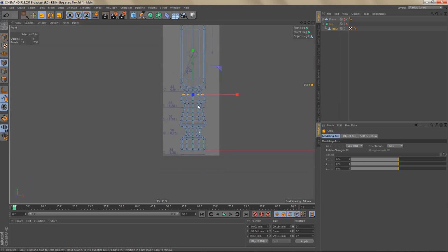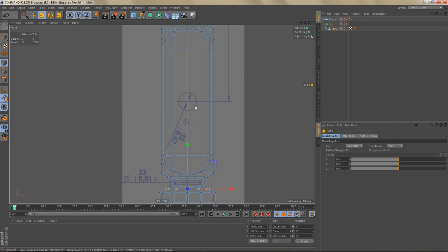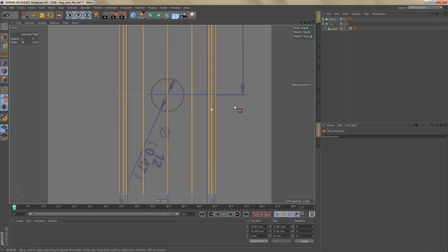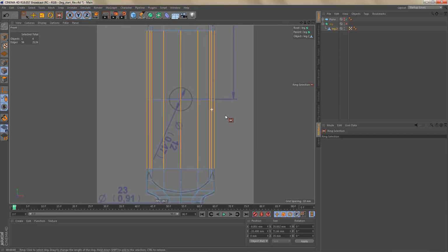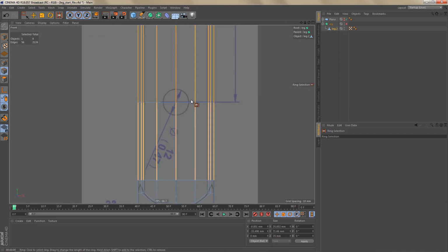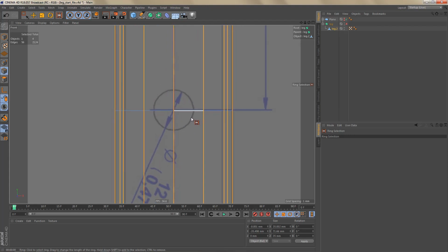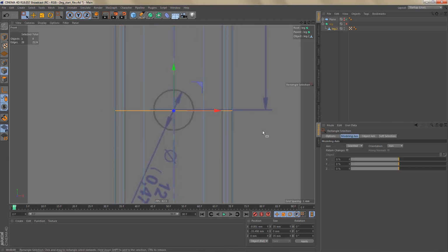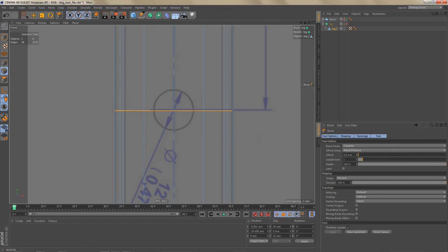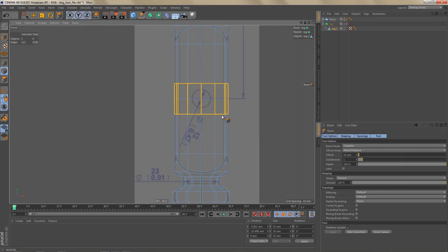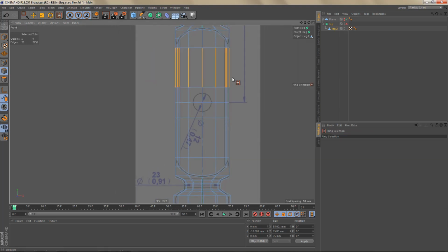Now, let's create the geometry for this hole here. I'm going to ring select these edges and connect them, and this should create the edge pretty much at the center of what we have in the reference image here. And I'm going to select these edges and bevel them. Let's do 10 millimeters with one subdivision again. And then I'm just going to add